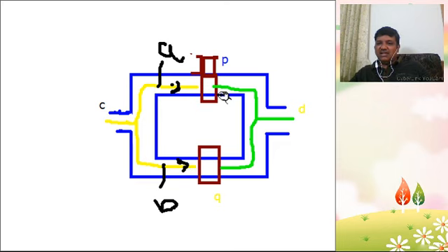So this is tunneling in the superconductor, and this superconducting junction is formed by niobium based materials, or lead based superconductors can be used. Niobium with 10% gold and niobium oxide as the insulating layer. So the back electrode can be niobium and the front electrode can be lead alloys. Like that, this sandwich structure is the Josephson structure, and the quantum mechanical phenomenon occurs when the waves are tunneling through this and reaching D.